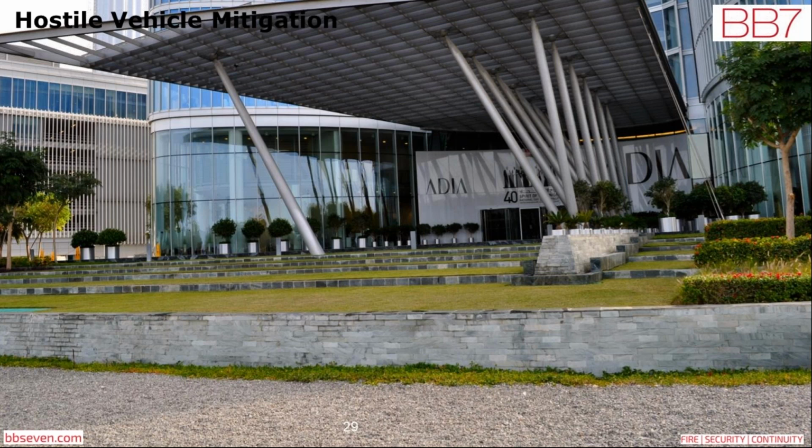Now here you can see a significant degree of standoff distance has been achieved completely through landscaping. The terrace landscaping stone upstand achieved vehicle denial without any security products. This is a purpose-designed HVM, but to the average person, this just looks like nice landscaping, which was the business image they wanted to portray.